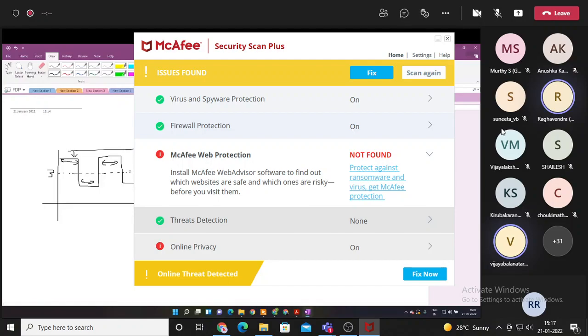After which it's the normal process: you do a simple time recovery, because you've done an upsampling, you then do a downsampling, and very importantly, we do Manchester decoding. After this, it's exactly the same as we did before. We detect the frames, and then I will send all of them to be demodulated. And it's all bits in this format. Since you only have two possible values, and since we already do a DC offset removal over here, this is similar to, you can say, your channel estimation and equalization.